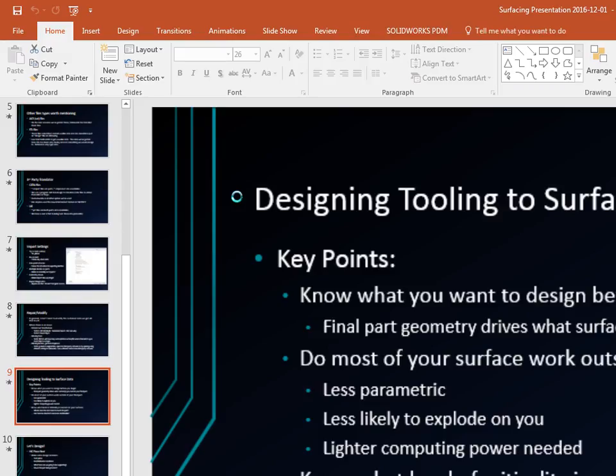Delete hole. That's one thing I didn't show on these top surfaces. One of them had a hole in it, yes, the 2 and 4-way locators on this part. So I just delete that hole using the delete hole command. To get that, you pick an edge and you hit the delete button. Maybe there's edge delete and delete hole. If you delete feature, it's going to delete that whole body, but if you delete hole, it gets rid of it.